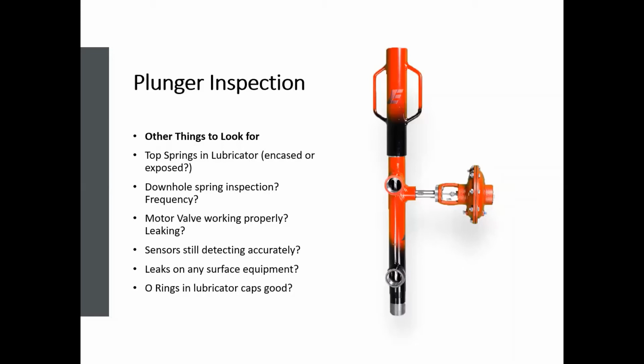Other things to look for as well: is your sensor detecting accurately? Are there leaks at surface equipment? You also want to check all your O-rings, your lubricator, and your caps, and things like that. Also, good practice to check your threads and flange connections to see if there are any strains or stresses.